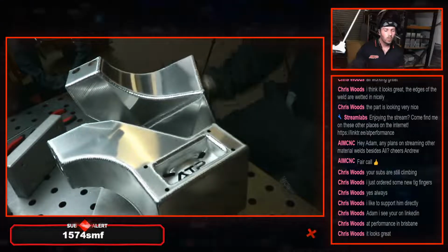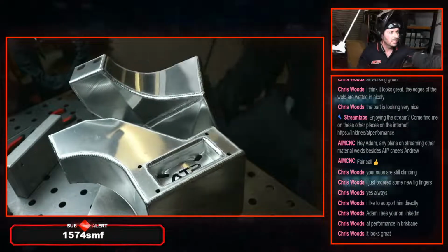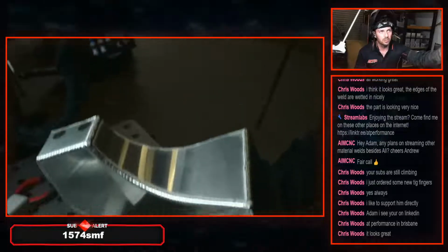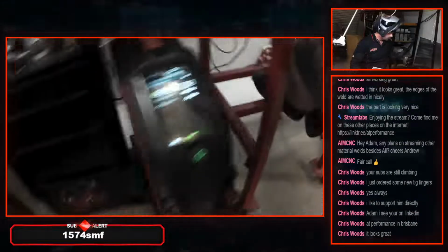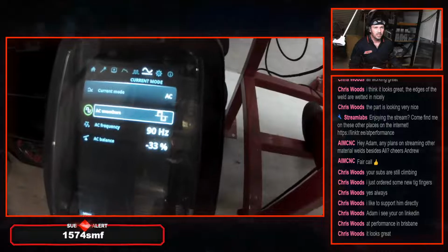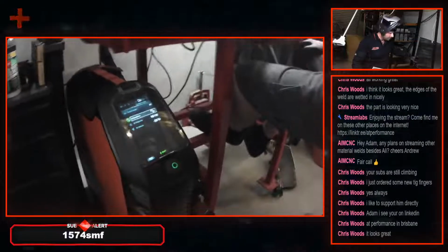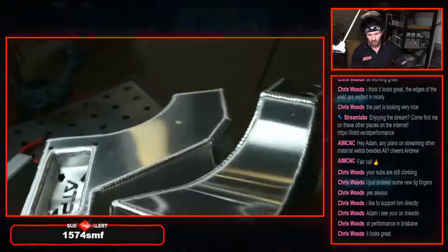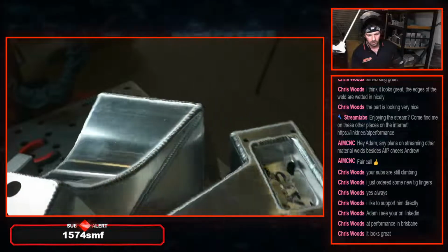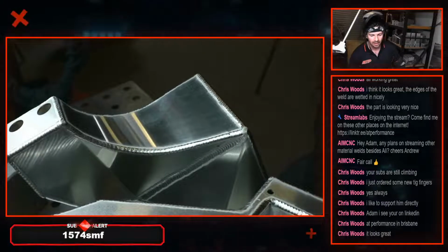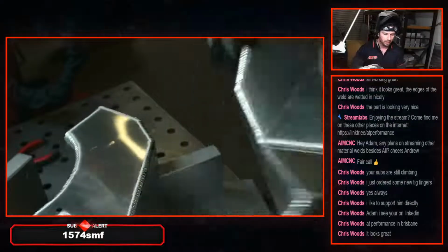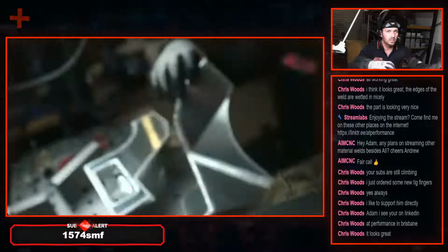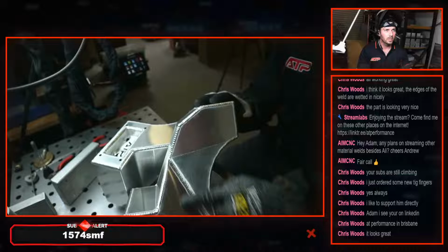When I flipped over and did the underside on this one, I did switch the machine over to square wave. I don't think I showed you guys here. I went to square wave. I was just trying to get a wider bead on that, and I think it was worthwhile. Not really sure. I think maybe I welded too much stainless steel today and just couldn't slow down for the aluminium. But really happy, yeah. That underside, like these welds on the seam at the bottom here look fantastic.